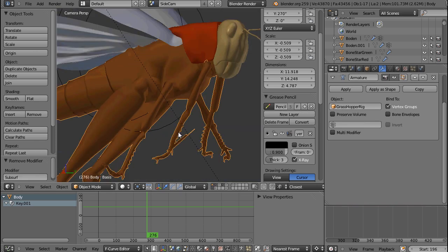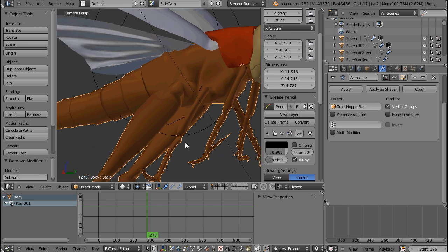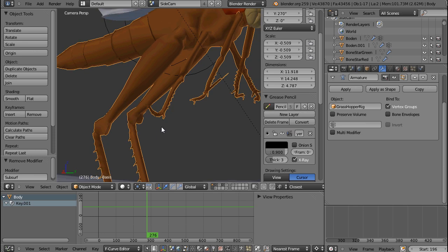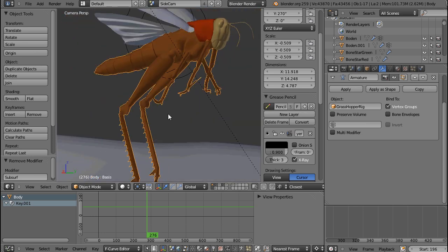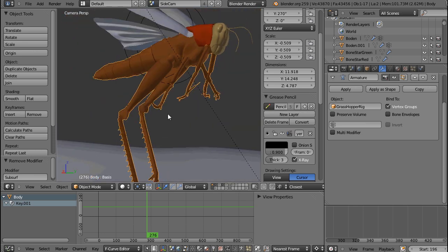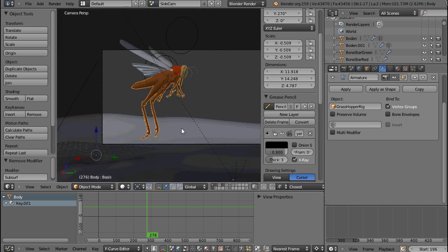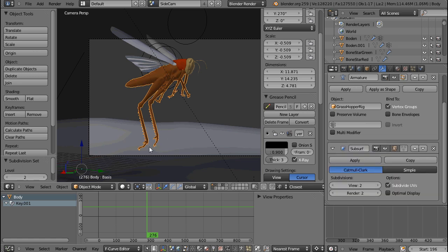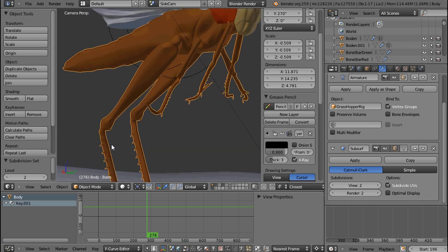As you can see, if I don't use the Subdivision Surface Modifier, I got a lot of jagged edges here, and it just doesn't look right. So, first of all, I thought, well, I don't need to make a tutorial about this one because I could just as easily write this sentence: go to Object Mode, press Ctrl 2. Presto. Okay, now my model looks a lot better.